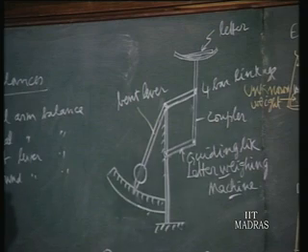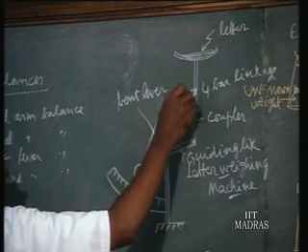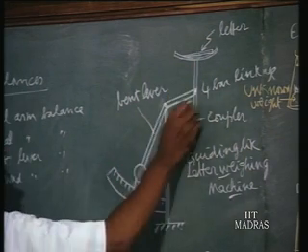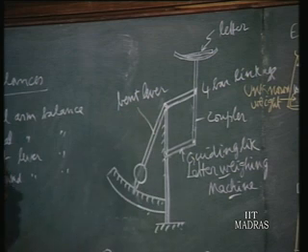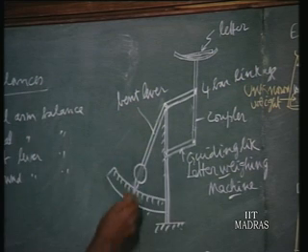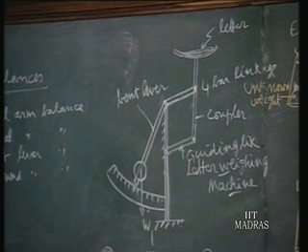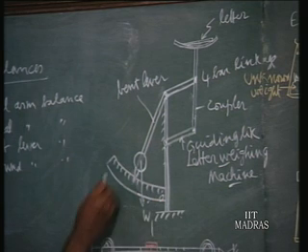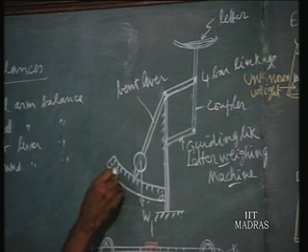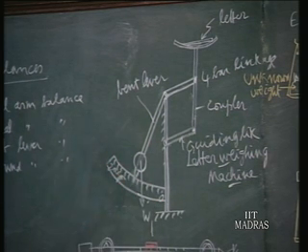That is an advantage. So when you put weight here, it acts at the end of the bent lever. So the bent lever tilts, and at the other end we have the weight W1, and where it stands, that itself is a pointer, and it moves over the scale. So from 0 up to probably 200 gram, we can measure in these letter weighing machines.